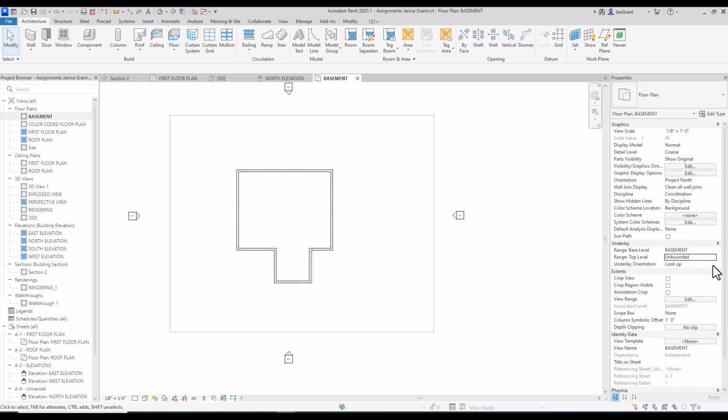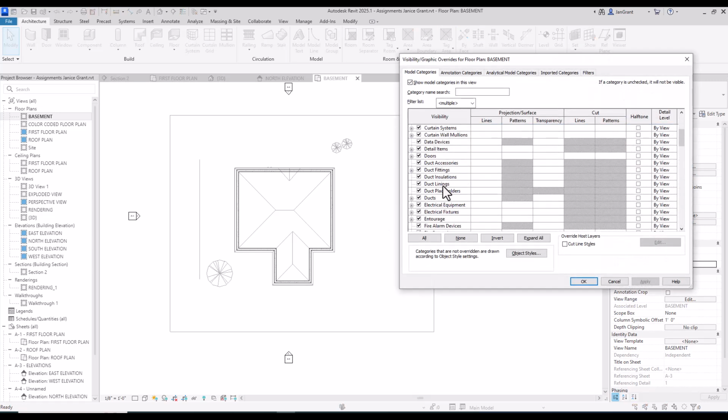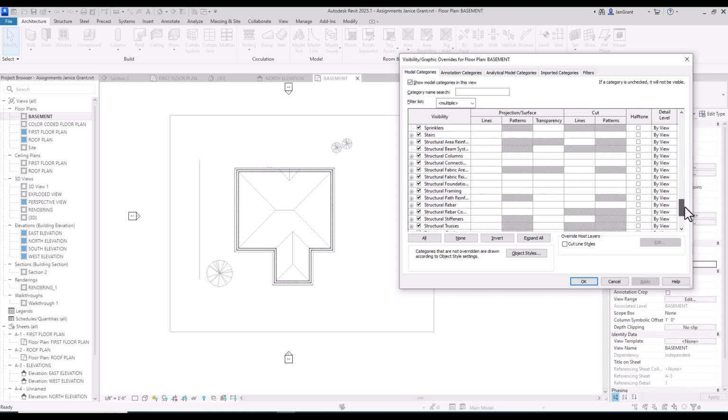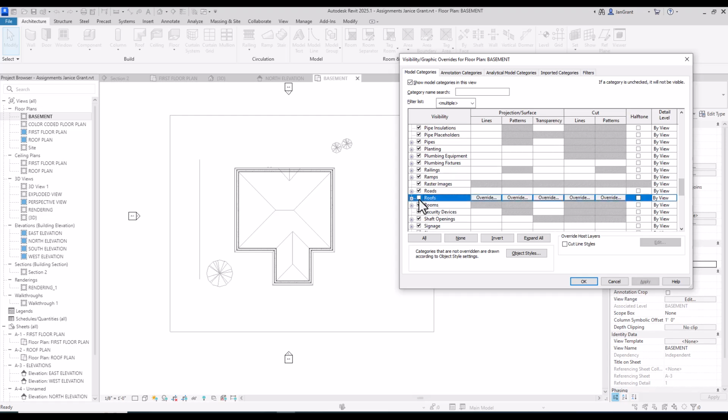And I'm going to then look down from up above and see this. So I'm seeing trees and everything else. But now I can type in VG and scroll down. There's always a way to figure this out. And take the check mark out of roofs and pick apply. This is how I was able to get to it.